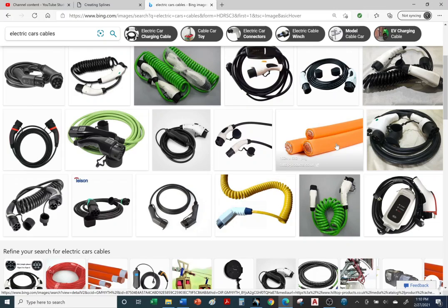And this has happened with some startup electric car vehicles where they try to take the cables and make a sharp turn, maybe somewhere near your gas pedal where it's running along the side of the driver by the door opening, by the door frame, and it has to make a sharp turn into the dash or into the firewall. And there's been issues where these have broken and maybe even caused fires because of the sharp turn. So you have to take that into account when routing cables.